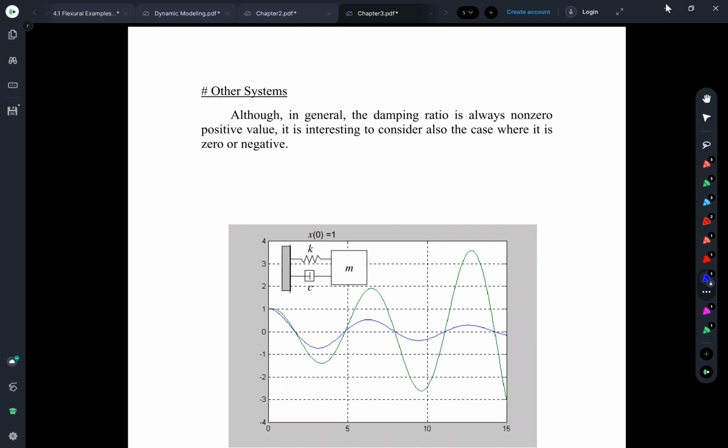But some engineers or researchers, if you remember the Tacoma Bridge, the bridge that collapsed under the wind, try to explain that with a phenomenon called galloping of the bridge under wind loading, causing what they call the negative aerodynamic damping.